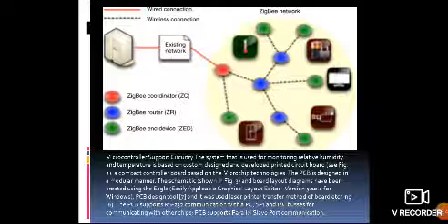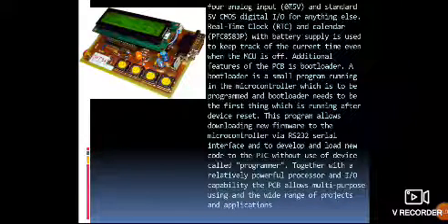Here is the microcontroller support circuitry. The system used for monitoring relative humidity and temperature is based on a custom design, and the printed circuit board and board layout diagram have been created using the Eagle PCB design tool. The laser printer transfer method was used for board etching. The PCB supports RS232 communication with a PC, and SPI and I2C buses for communication with other chips.